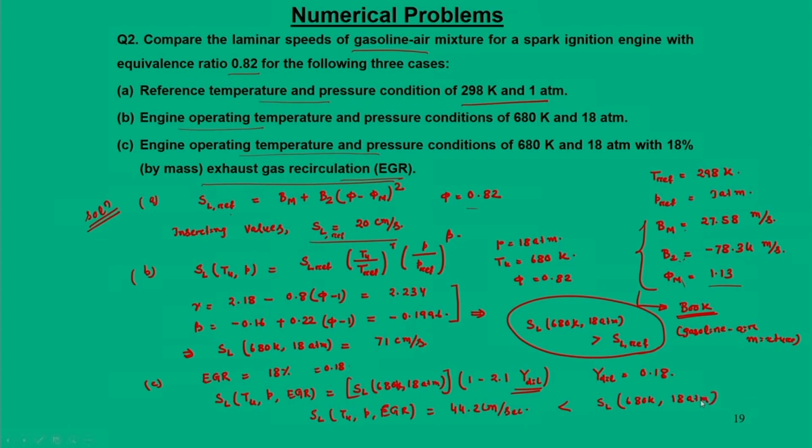What it says is that exhaust gas recirculation decreases the flame speed, and higher recirculation of EGR will have a great consequence in terms of flame speed, because it can arrest the flame to almost 0 velocity. So, there are limited situations in which exhaust gas can be introduced, up to a certain level.